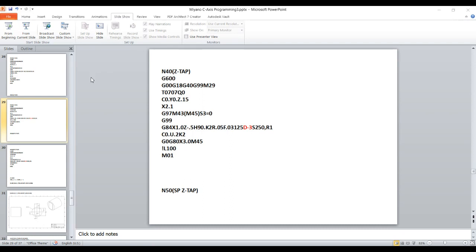Pretty much the same thing. On our Mitsubishi control, you have a choice: G12.1 D1 E equals C, or G12.1 D0 E equals C. If you select D0, your programming is on the Y-axis. If you choose D1, the C programming is inside of the G12.1.